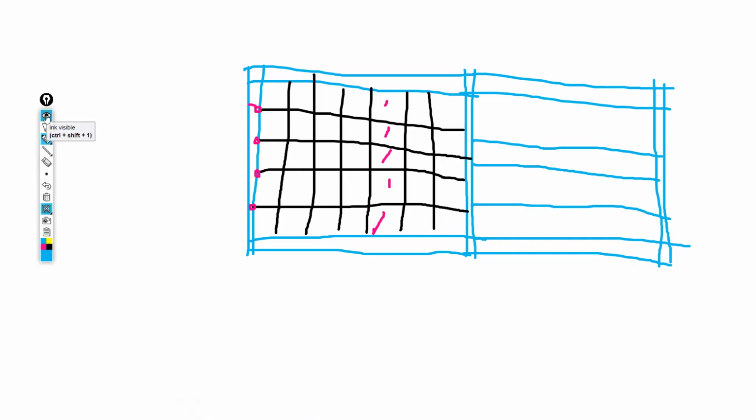Yes, we have the ribbed slabs, but the loads that are being looked at here are loads of the solid slabs, not ribbed slabs. For ribbed slabs, they're already connected to the beams just by virtue of their span direction. It is okay.